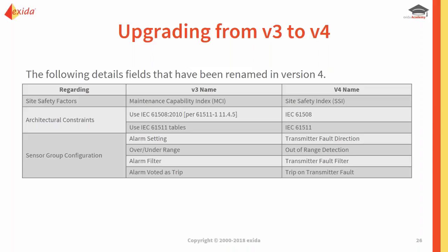There's an explanation to this, but it's easier to read what we wrote down before than me trying to remember exactly what we wrote. But this has to do with the mean detection time, the mean repair time, and the overall MTTR. And there's actually a contradiction in the standard that leads to some people misinterpreting how you need to calculate the safe failure fraction.